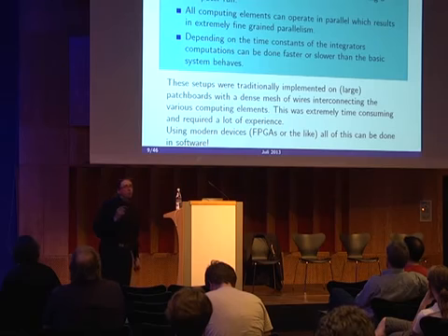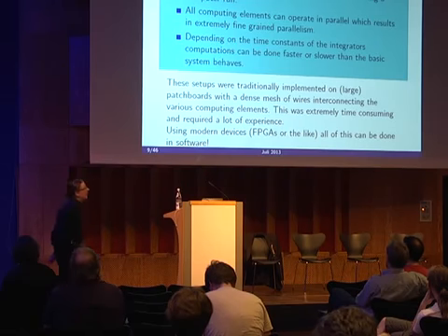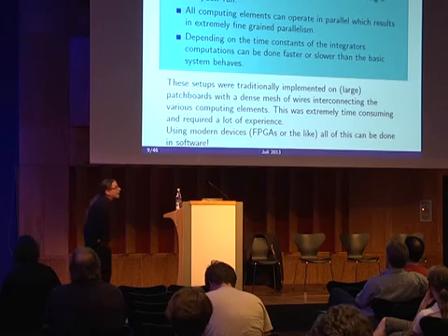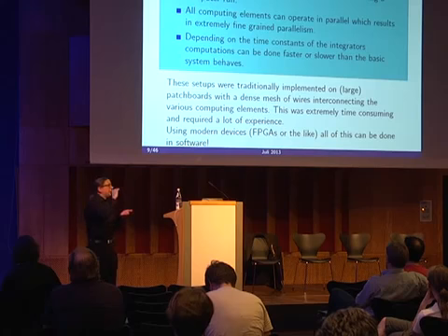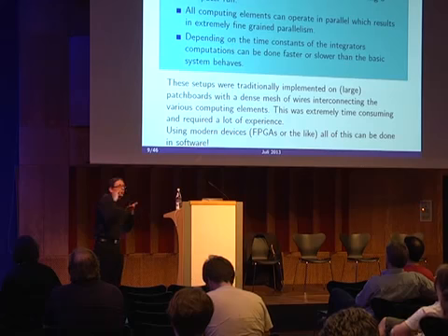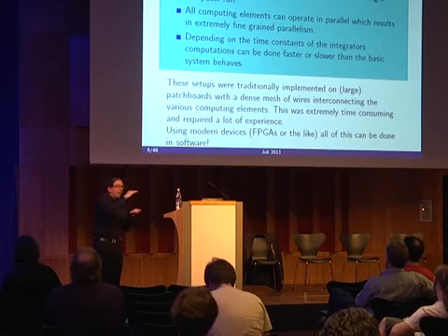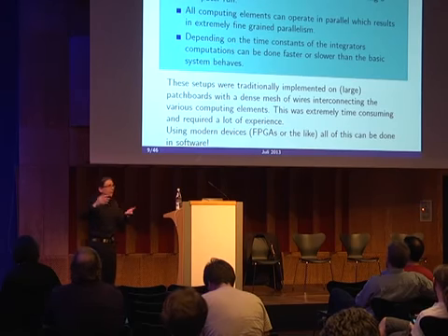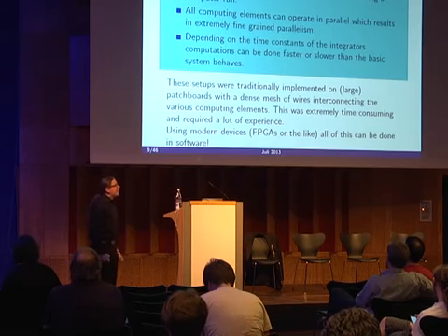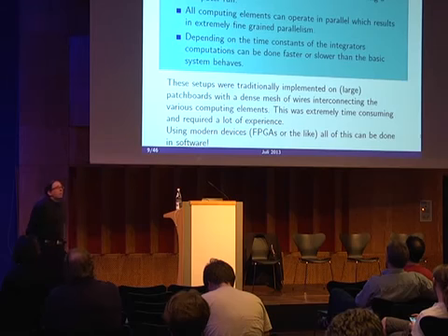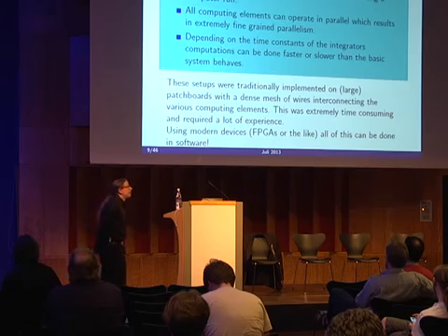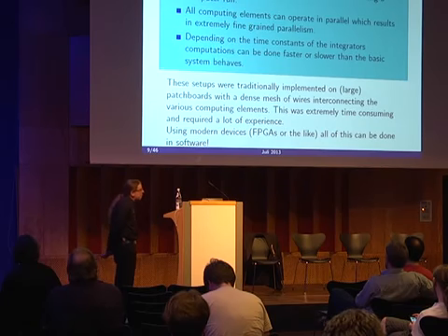A basic problem in programming analog computers is called scaling. A traditional electronic analog computer has a problem. It only has values between, for example, plus minus 10 volts. So you have to squeeze your variables into this area of values which can be used in the calculation. This makes solving stiff differential equations and the like very, very hard on a traditional analog computer. But using modern technologies could make this problem much easier.